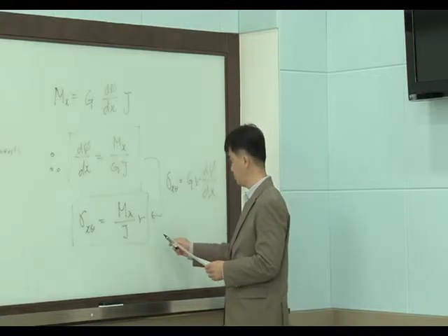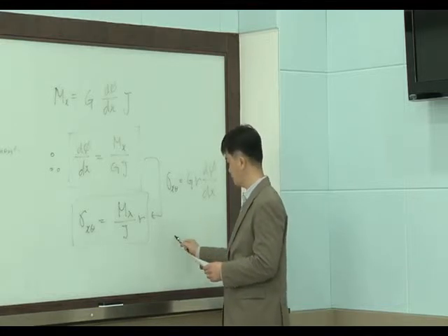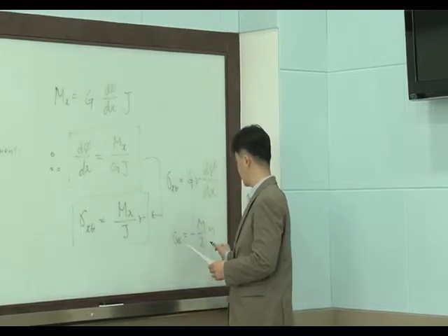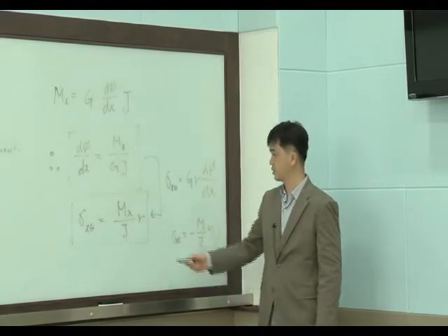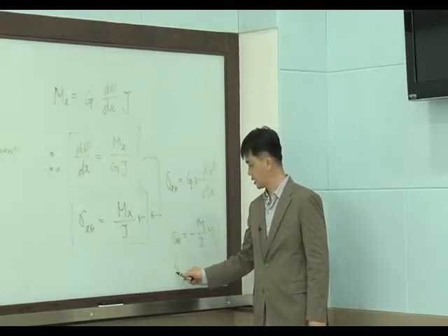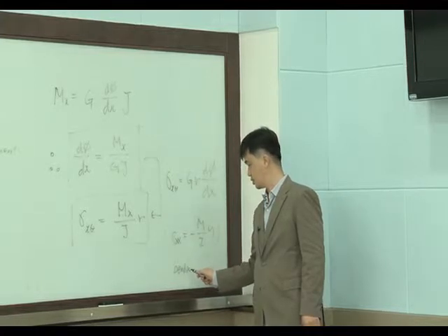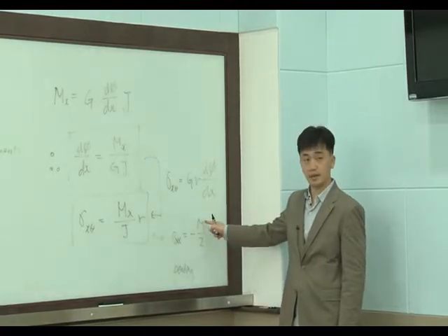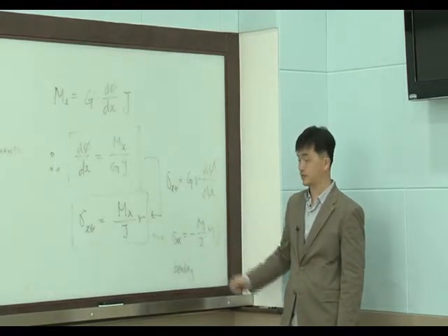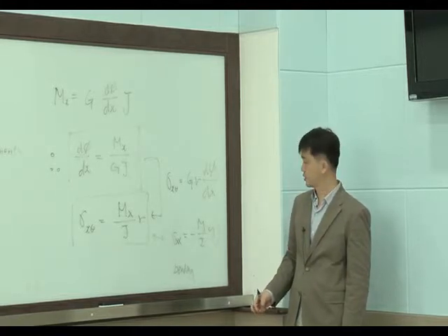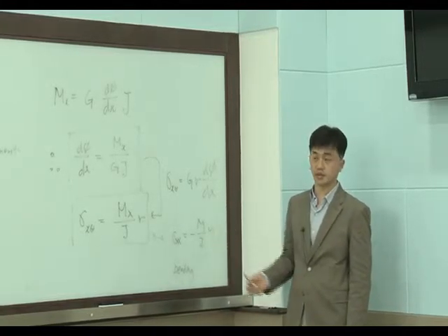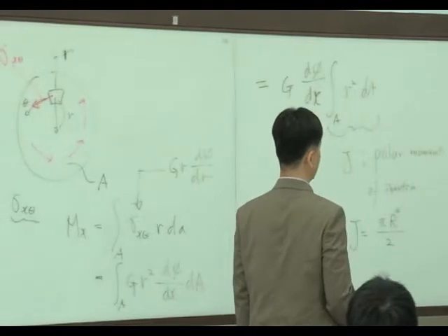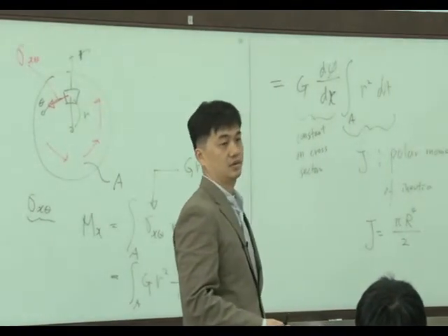So in the beam bending case, stress xx was minus M y over I. Right? Very similar, looks similar, right? Beam bending. So compare both equations. Very similar, right? M is a bending moment, I is the second moment of cross-sectional inertia, and y. Very similar form. The only differences are I and J, R and y, and the type of moment.